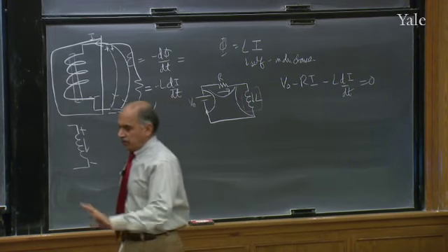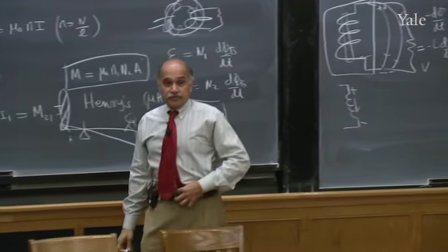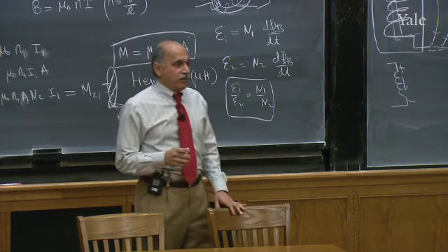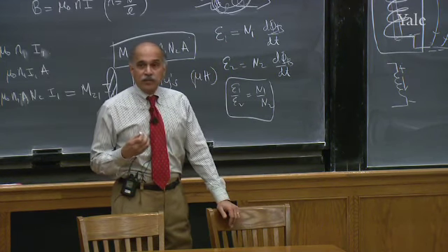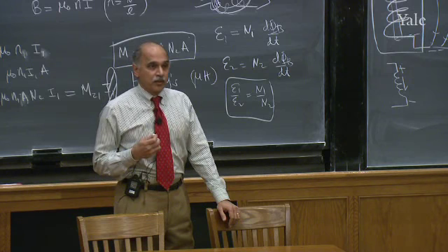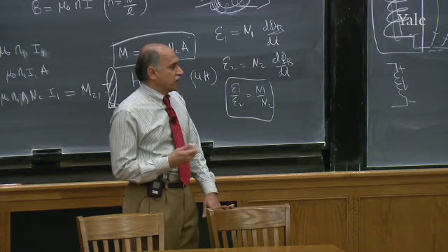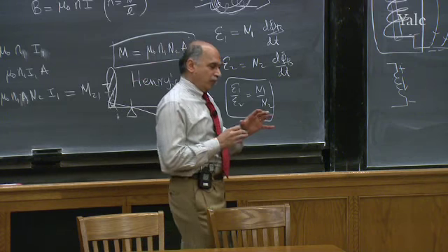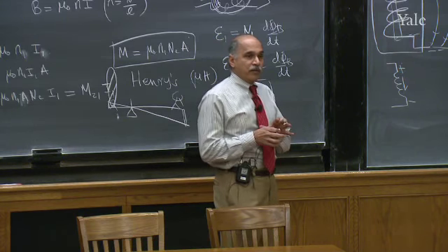So here's a one-word summary for those of you who have heard enough. We learned the notion of voltage or a potential can be defined only in a conservative problem. But a changing magnetic field in an inductor definitely is producing a field which is not conservative. So if you go deep into the coil, you will have problems defining voltage.